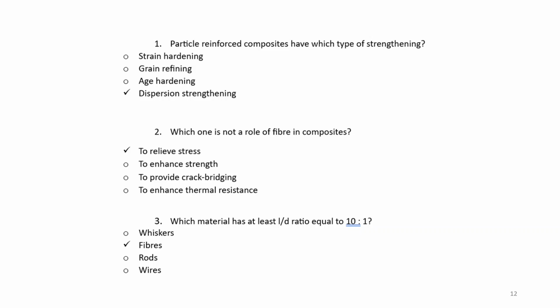Okay, in case of fiber, it will also provide good strength to your material by taking some part of the load that is applied on the material. Also, if a crack is propagating, it will be bridging the crack. So crack length will keep on increasing and it will require more and more load for the ultimate fracture of the material. And it will also enhance thermal resistance of the material and it won't be relieving any stress.